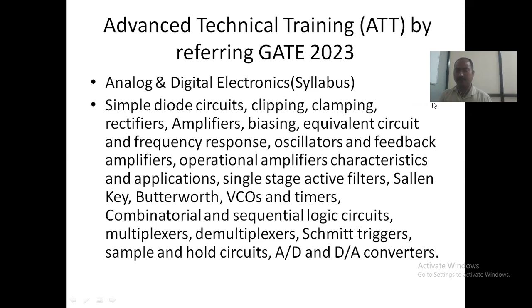If we apply a sine wave and we get a cos wave, and that cos wave is again applied to the input, it indicates negative feedback. If we apply a sine wave, we get a sine wave, and that sine wave is again applied to the input, this is called positive feedback. That positive type of feedback is used in an oscillator. The application of the oscillator is as a sine wave generator. The amplifier is used to increase the input signal strength. That's the application of your amplifier.